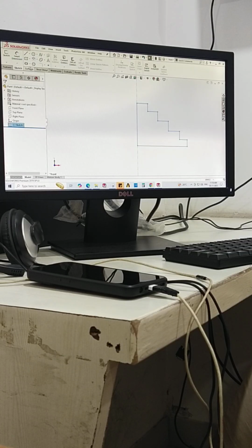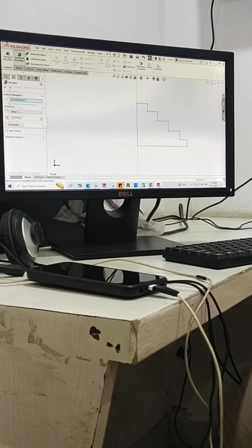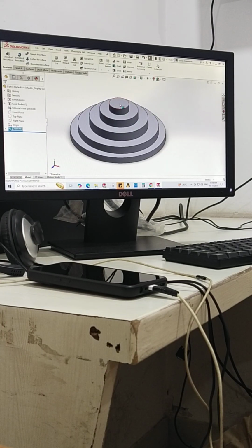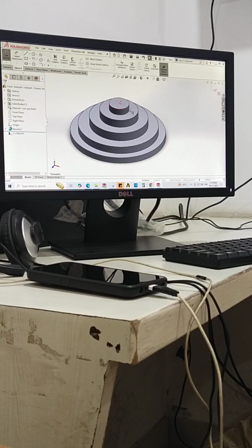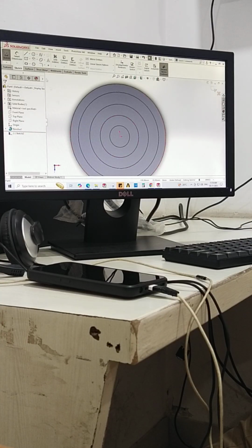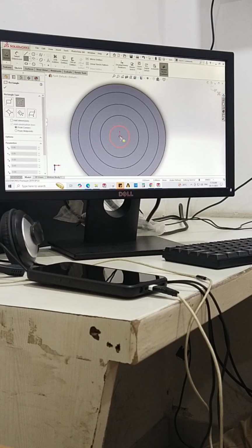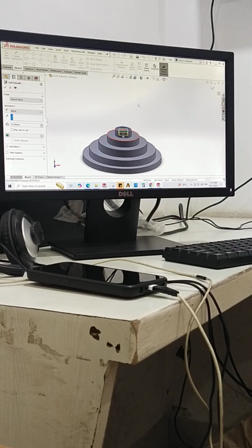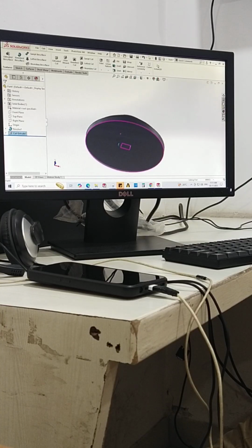Exit. Click, revolve. Okay. Now extrude cut, top line. I want to make a rectangle. Here we should go fully through, up to last. Up to last is through all. Can you see? Through all.